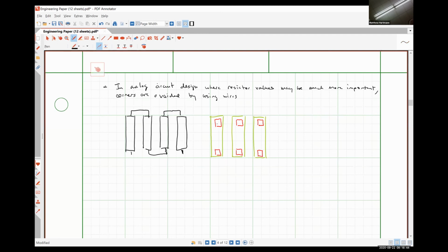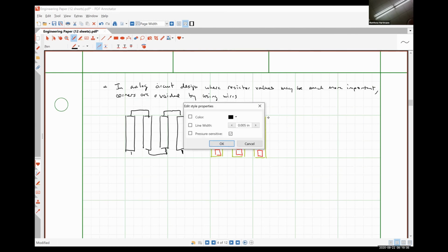Then we would put in a via. There's a little plug of tungsten. Now in practice, putting only a single via is typically avoided, because if it ever wears out, you no longer have a complete connection.